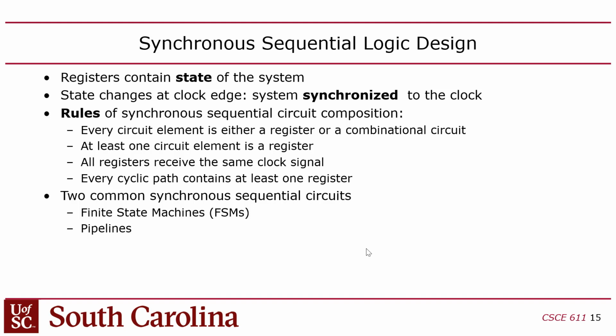You'd have to fetch, decode the instruction into control signals, and then activate the ALU and write the value back in the register file, all within one cycle. That's a lot of things to do in one clock cycle. So we break it up into 3 cycles and then have 3 instructions being executed in parallel in order to speed up the throughput. I have another lecture about timing analysis where I'll talk specifically about why having those long paths is bad.